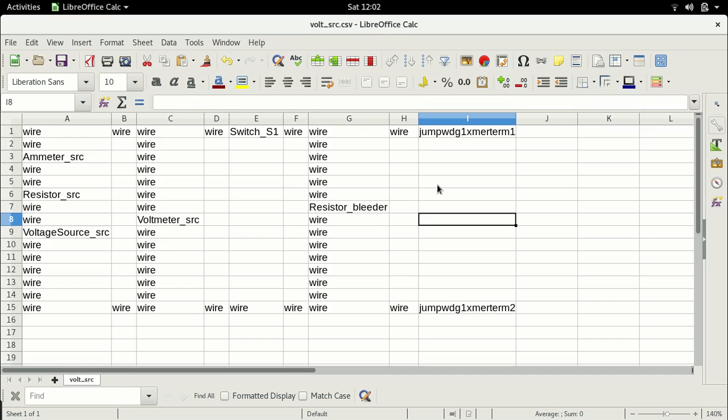You must not break the current in a transformer, right? When you're energizing a transformer, the magnetic field builds up, the magnetizing current increases. This magnetizing current should not be broken to zero. If this magnetizing current is broken to zero, the energy in the transformer has nowhere to go. Alright, that is not at all recommended. Right? So therefore, this arises that what do we do with the energy in the transformer?